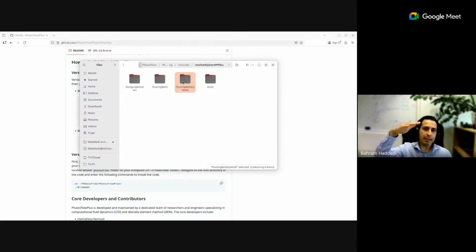For example, if there is an interface, then we can just resolve the mesh on this interface, if this interface is the most important thing that we want to capture. Everywhere else, the mesh is coarse, and just on this interface, the mesh is fine. But we know in a multi-phase flow, this interface is not a constant thing, so it's moving during the time. Therefore, we use this dynamic mesh. Basically, the dynamic mesh tries to detect this interface, and based on the location of the interface, it tries to refine and unrefine the mesh in these locations. We will see how this can be set up and how does it work.